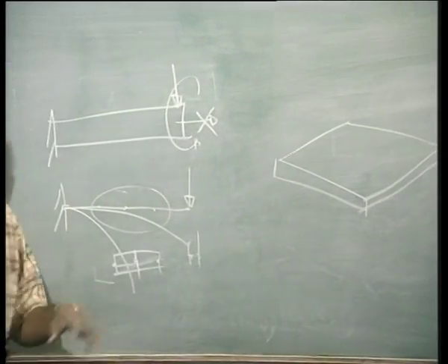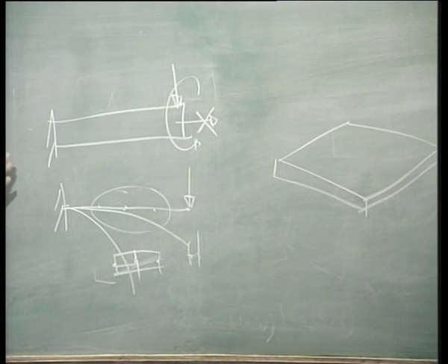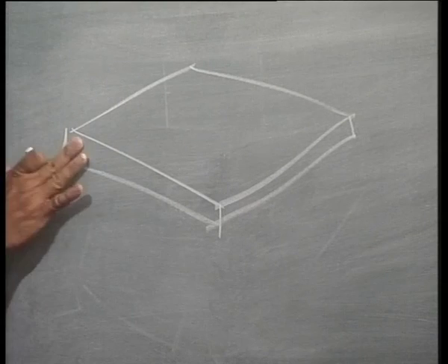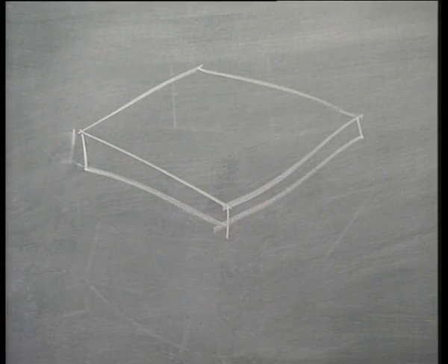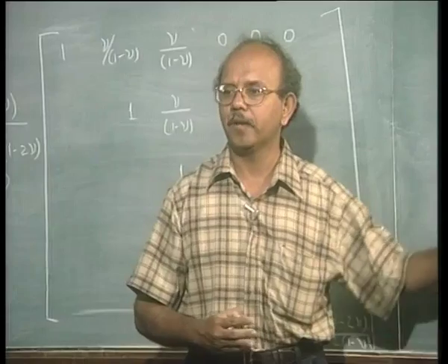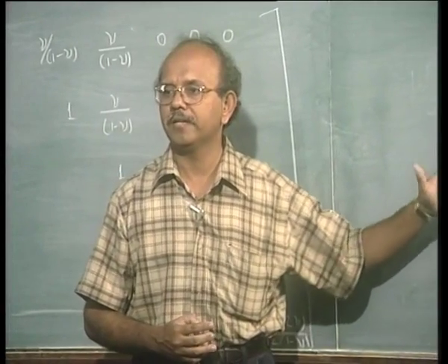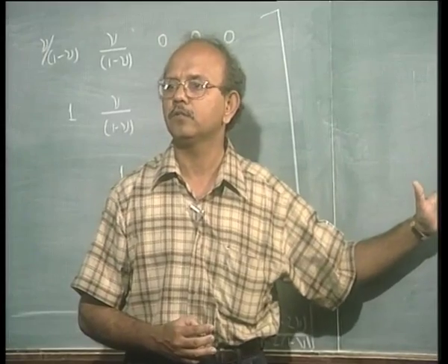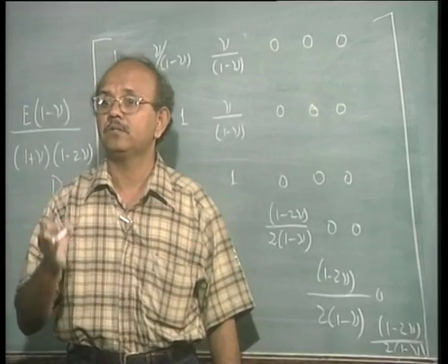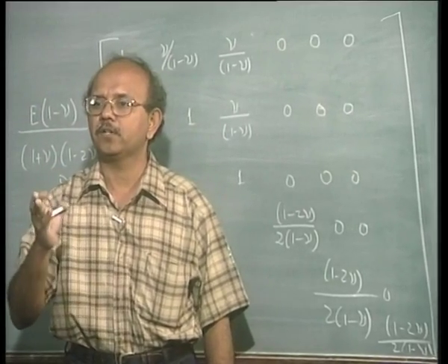See, there are a lot of assumptions, yet we have not come to all that in a beam. The assumptions that you had when you did your beam theory in earlier classes still hold good. What are the assumptions? Remember? Isotropic is general. Yes, that means planes remain plane and they remain normal to the neutral axis. So what does it mean? Shear effects are not there.